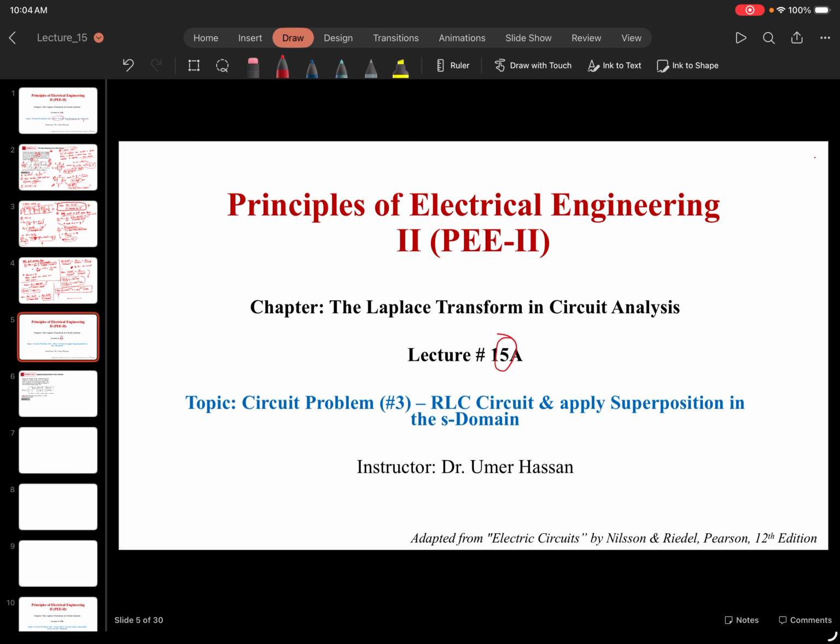Again, in this chapter, we are applying Laplace transform applications on the circuit. In the previous chapter, we looked at how we can model a resistor into a Laplace transform, which essentially remains a resistor. Ohm's law remains the same, and resistance comes out to be constant, right? And then we also looked at how to model a capacitor and an inductor with the initial energy stored. Then we came up with these two different models, a parallel and the series one, and we discussed how to pick which one in which kind of applications.